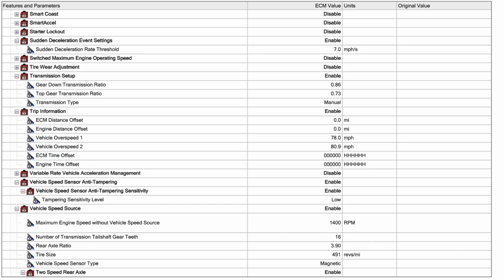You can also use starter lockout so that once the engine's running, the operator can't try to start it and grind the teeth off the starter. That happens in situations like a vac truck where there's a second engine on the truck and the thing's roaring, and he forgot that he left the engine running, can't hear it. They'll get in and try and crank it. So that's what starter lockout's for.